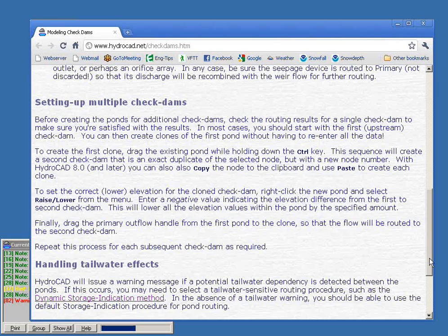So that is basically the material I plan to cover today. One of the things you want to keep in mind as you're doing this is that HydroCAD is an event model, that we are dealing with a single event of perhaps a 24, 48-hour storm, something of that nature, or even shorter. And so we're dealing with the short-term flow effects. We're generally focused on peak management, whereas a lot of your LID elements are focused on very low volume events. It might be a 1-inch event or a 1-year event or something of that nature.